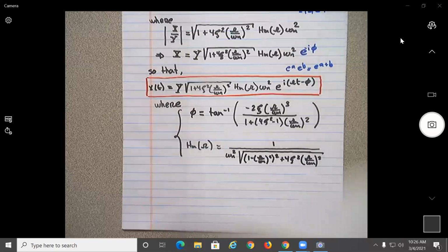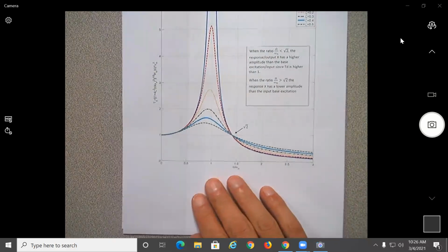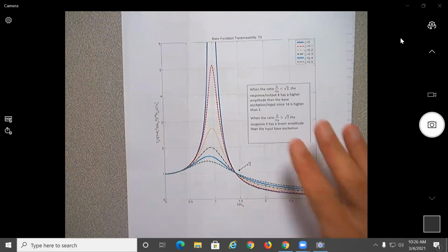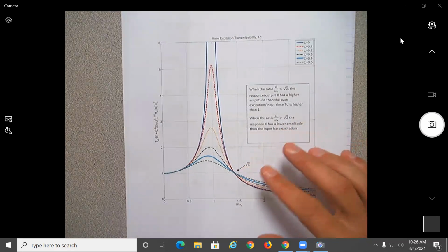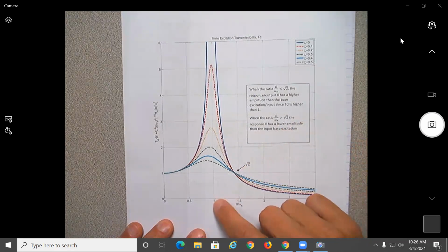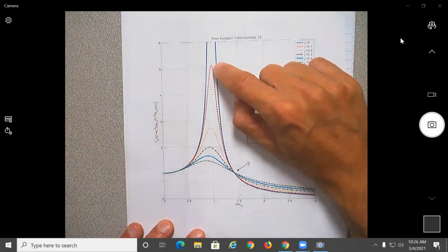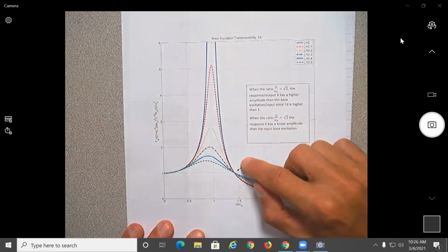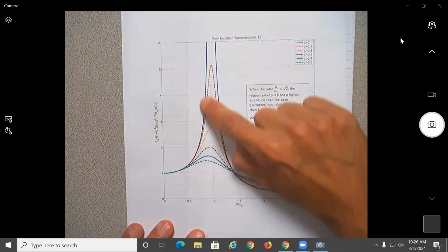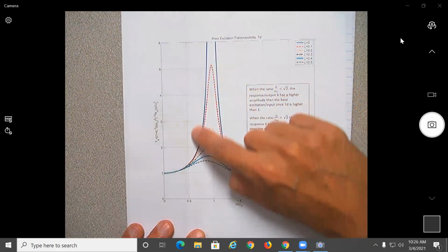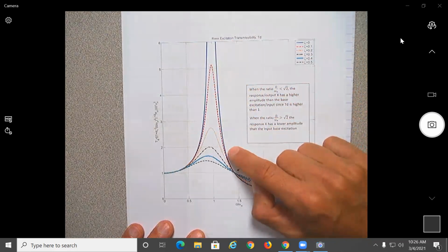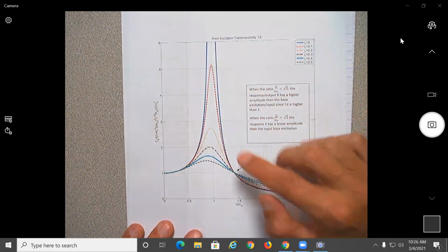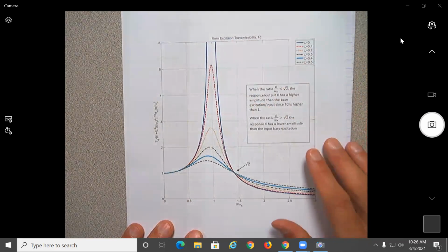Okay, so in here, this is more or less the same figure as we had before. Remember, for the force frequency, second degree of freedom, what does that mean? If this is equal to 1, this is the resonance, no? What happened at the resonance? We see that the amplitude goes to infinity. All right. So what is the function of the damping? Is to round off and diminish the amplitude at the resonance. Okay. But that's what we had for the force. So in this case, what happened?